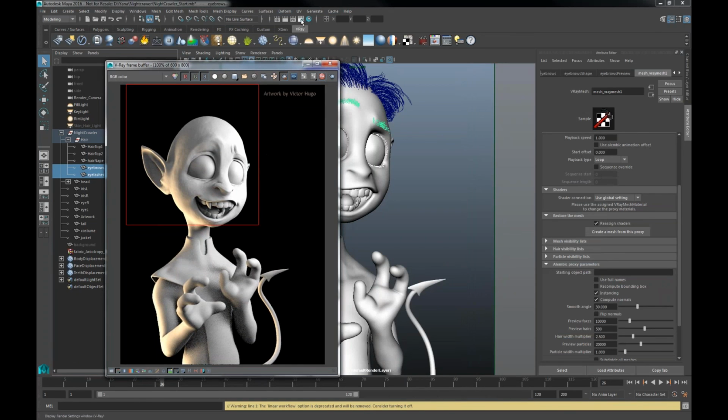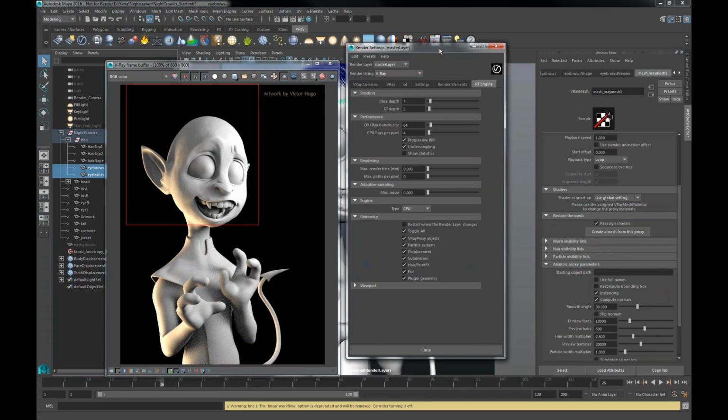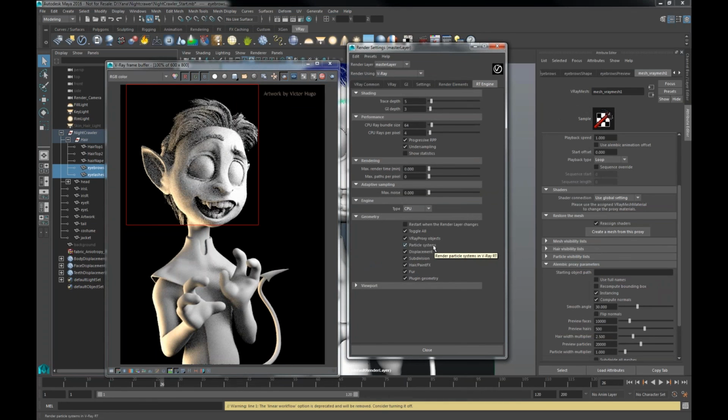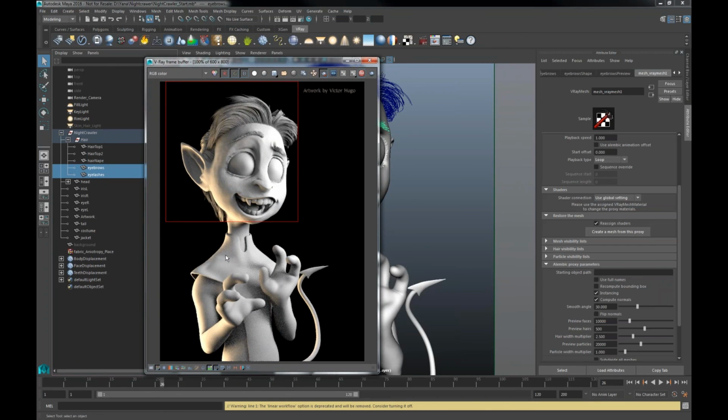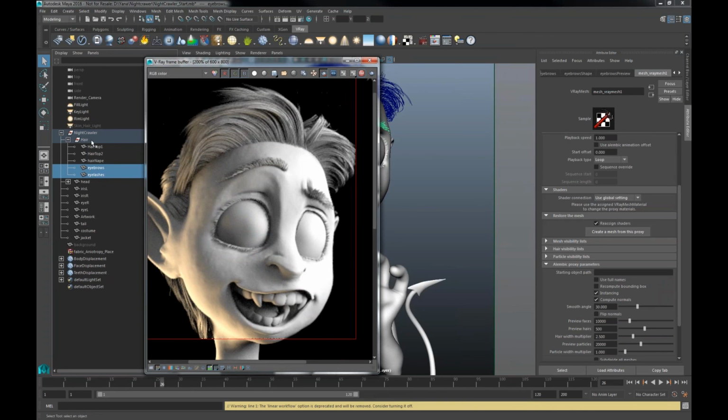And again, make sure you have here, in my case, I need the V-Ray proxy enabled because I'm importing the hair as an Alembic using the V-Ray proxy. But if you have a Maya hair, make sure your hair here is checked so you can see it in the RT. All right, and now I can play around with the thickness of the hair because I have this control directly in the V-Ray proxy.